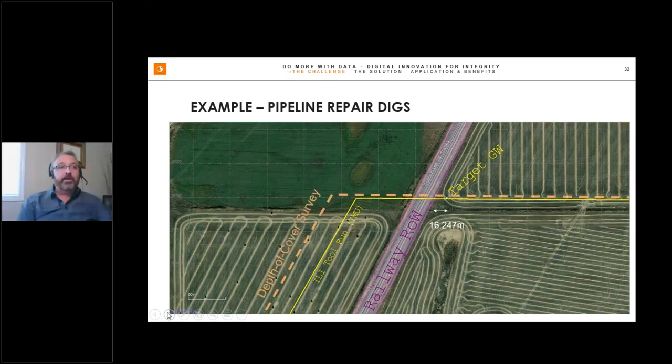However, what happens when I introduce another data set from a different source? The orange centerline is based on a depth of cover survey conducted a few years previously, and it deflects from the ILI trajectory prior to the crossing. A closer inspection highlights an east-west difference of approximately 20 meters at the bend. This data overlay suddenly calls into question the target girth weld position and introduces a variety of possible execution strategies that will range in both time and budget.